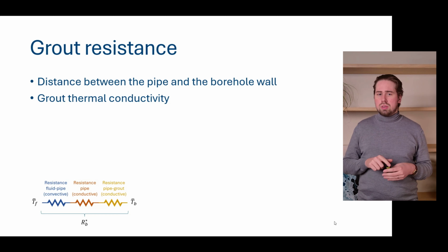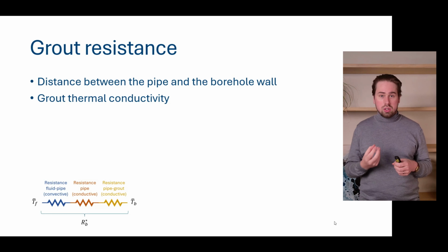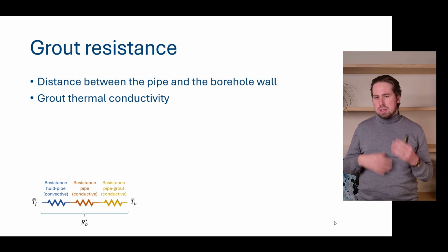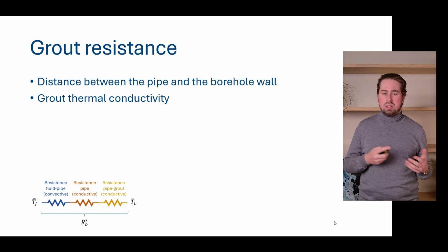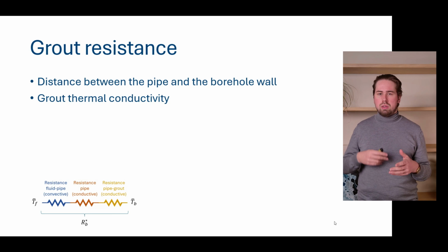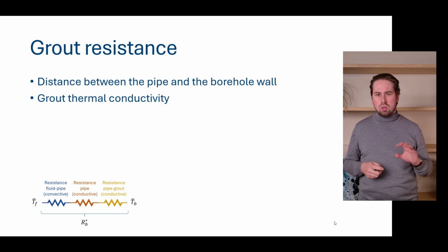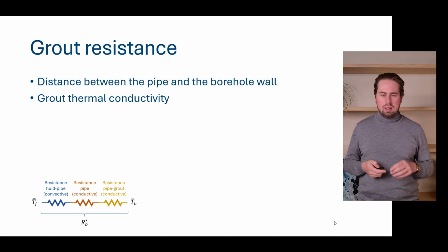Also, on another note, not all boreholes are grouted. For example, in Scandinavia, where they drill the boreholes into solid rock, they typically just fill it with groundwater and install the probes in it. Here it's way more difficult to actually know what your conductivity will be, because the water can also move up and down, and you have convective effects. We've written a couple of sentences on our website in the textbook to explain a little bit how that works.